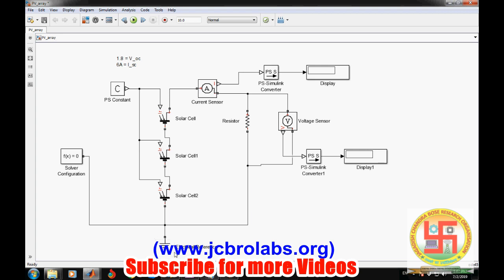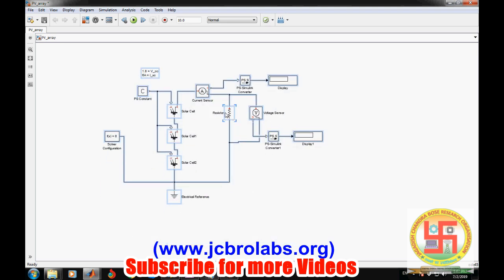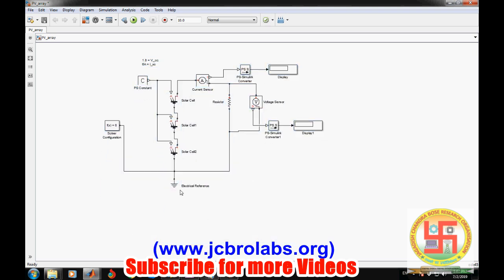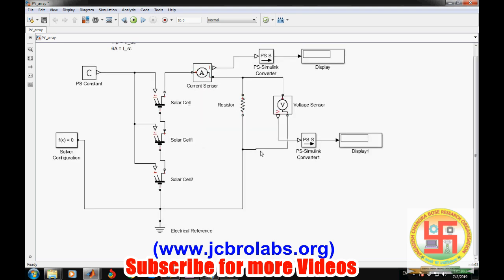You may be getting some problem here, so let me show you the circuit diagram again. Here it is. We have connected the reference. The only thing we have changed is that we have now connected 3 cells in series, so it is a kind of single solar cell which we have made. Let's zoom in a little bit. Similarly, we are going to measure the current and the voltage, with a similar resistance.